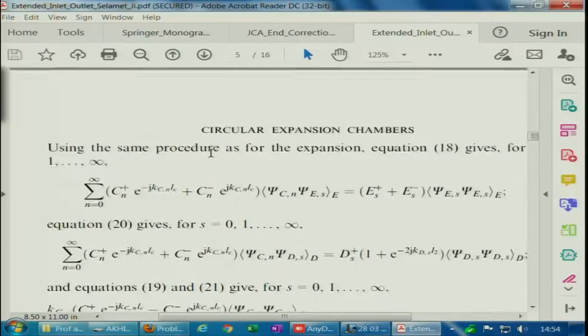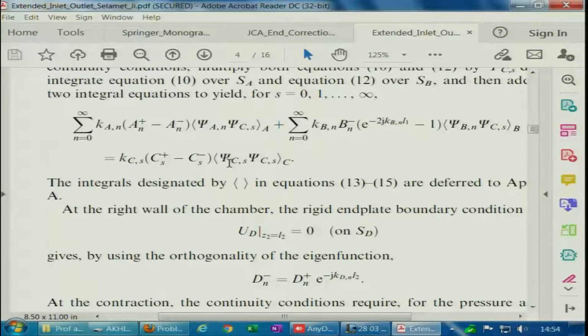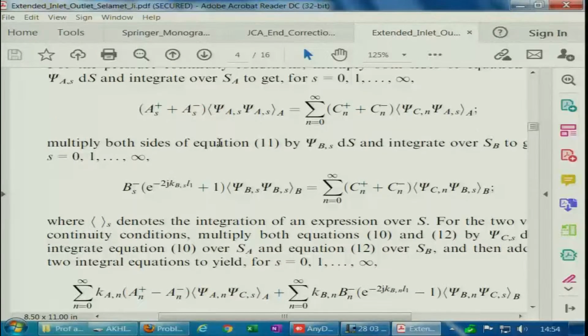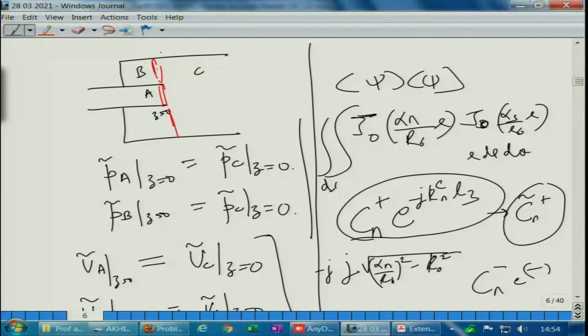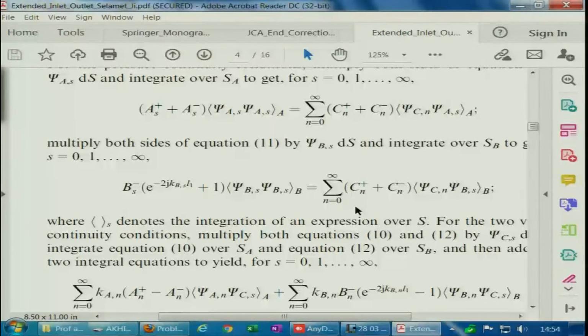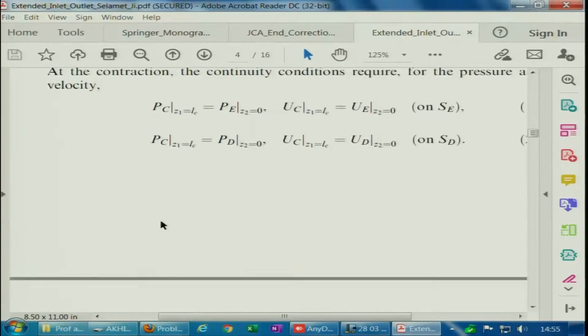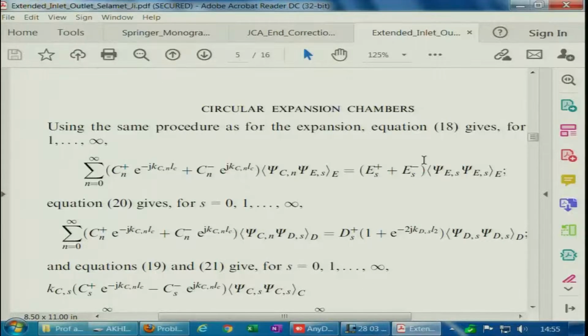What do we do? Now, at the other boundary conditions, there is something that I want you to understand properly. So, here also we have these 3 equations. So, if we are setting this guy as like this, we cannot increase our number of coefficients. You see how many set of coefficients we have? We have A minus reflected waves in the inlet pipe, forward travelling wave, negative travelling wave in the chamber, and B minus. So, 4 sets of coefficients, 1, 2, 3, 4, and similarly we have, this is set to 0, 5 here and 6, and these two are known.